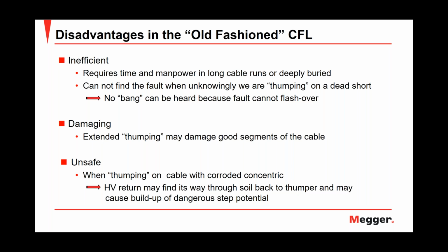It's inefficient because it requires time and manpower in long cable runs or deeply buried cables. For instance, let's consider that we have a 1-mile cable and we have the fault 26 feet before the far end. If I have connected my surge wave generator or my jumper at the beginning, at the near end of the cable, that means that I will need to take a long walk to find the fault. For this reason, we said that it requires a lot of time.